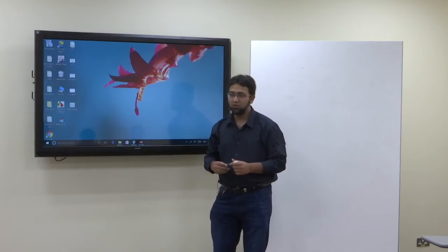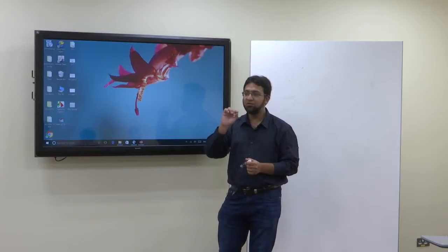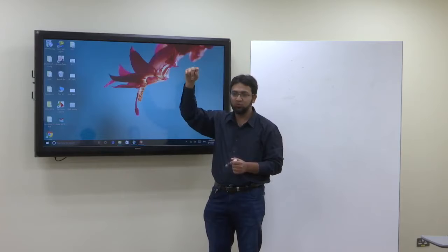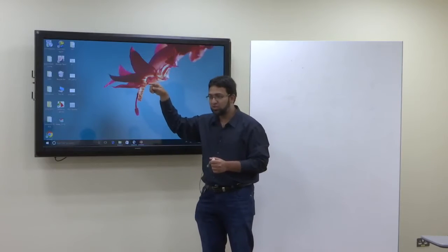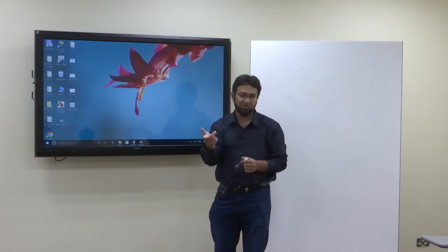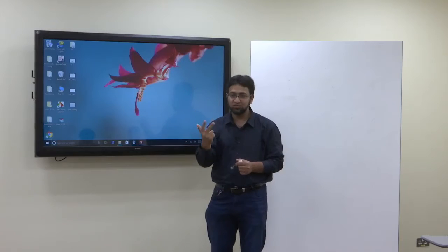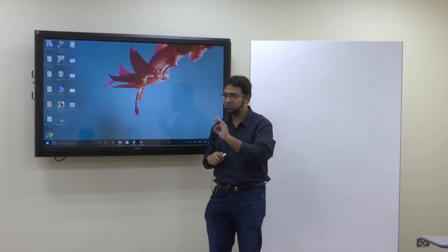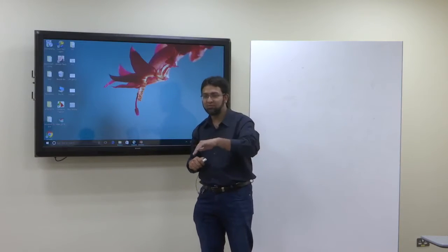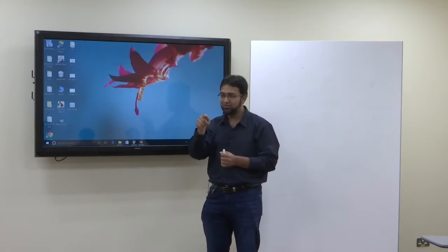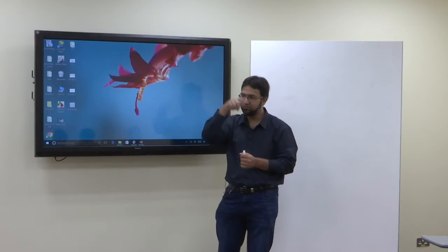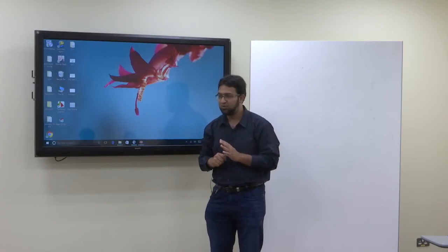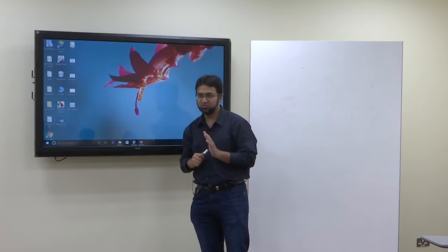Okay, so this is a very important curve, and you need to understand all these stages, from point O to A, then A to B, B to C, C to D, D to E. What is happening and why is it happening? This video explains two things: what is happening and why is it happening. So this is something, the curve itself and what is happening and why it's happening, and the names: Leiden-Frost point, critical flux, onset of nucleate boiling. These things are all important for the short questions point of view. So consider this video as a very important one.